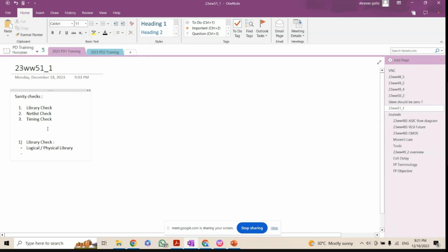Again, see, if it is not meeting that path, again it is not meeting, right? To be honest, it happens in our real time projects. So again, it's a kind of iteration, you need to make a lot of trial and errors. So you should not get fed up with this process. So again, you need to go back to this stage. Okay, now you decided routing is not fixing. Now you decided floor planning is also not fixing.